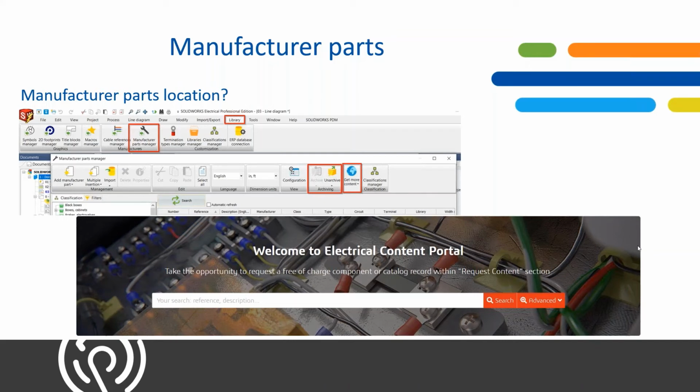This is what's going to bring you to your welcome menu. You just sign in, and then you have access to all of those symbols. Okay. Once you have all those symbols, all you're going to do is unarchive that and bring all of that information in, and that's going to be locked in. It's going to be downloaded to your electrical schematics. And now you can go through and search through your filters for whatever particular components you may be looking for, and then attach that to your symbol.